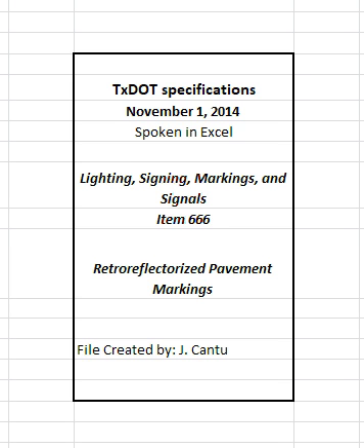The engineer may decrease the mileage frequency for measurements if the previous measurements provide satisfactory results. The engineer may require the original number of measurements if concerns arise. Restripe once at the contractor's expense with a minimum of 0.060 inches, 60 mils, of Type 1 marking material if the average of these measurements fails.